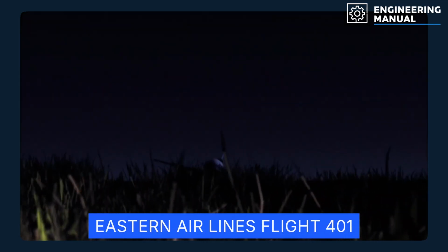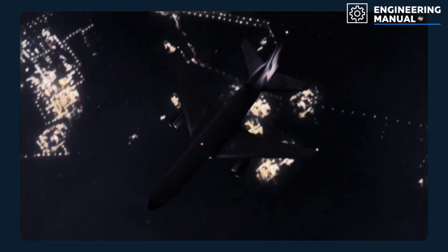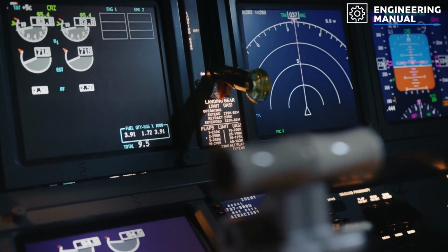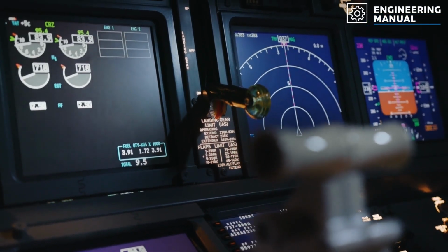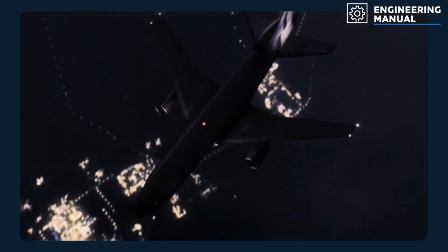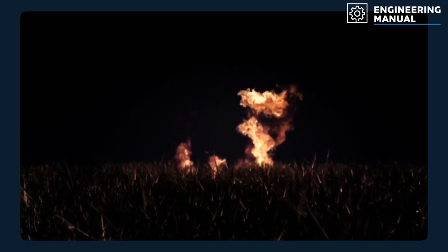A historical case underscores this principle. In 1972, Eastern Airlines Flight 401 crashed after the crew became distracted by a faulty landing gear indicator light. The bulb failure itself was minor, but the event showed how a small issue, if not handled properly, can pull attention away from more important system states. Subsequent cockpit design increasingly emphasized redundant warning systems and cross-check logic to prevent single-point distractions from cascading into disasters. The lesson extended beyond aviation. Redundancy must address not only hardware failure, but also human factors.